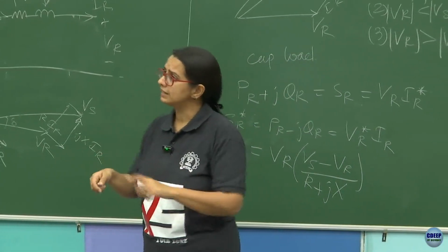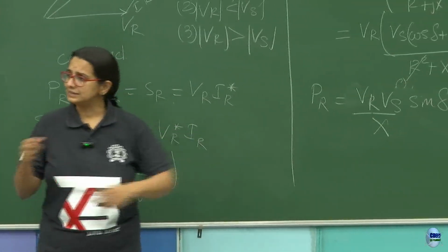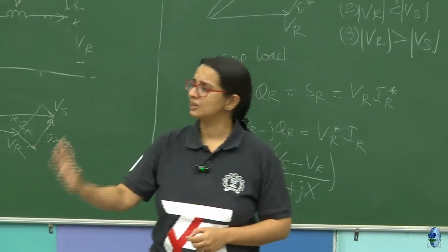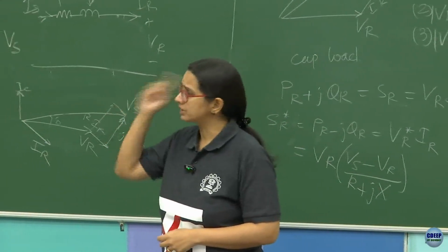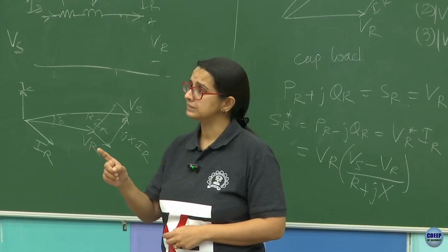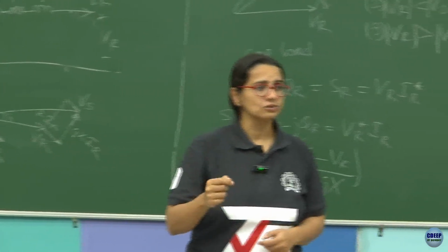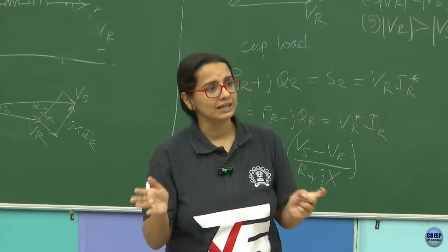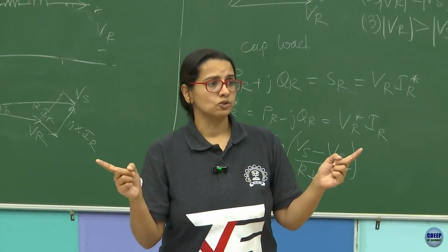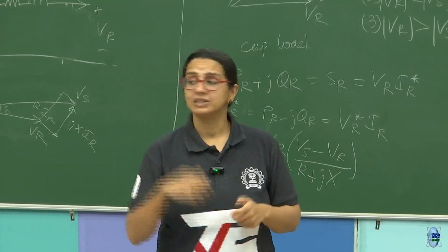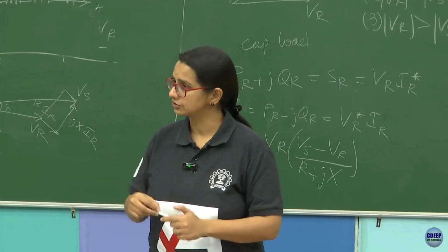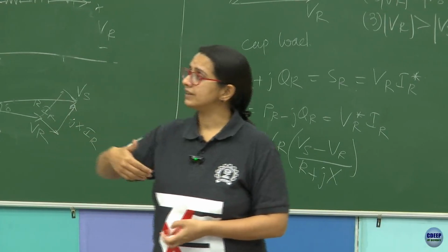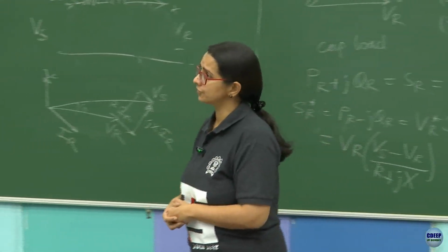And based on that, they're going to look at this and then say, okay, for this corridor, this is how much power you could safely push. It's going to be a function of what corrective measures for voltage are in place, what they think from their intuition is a safe enough delta to maintain across the sending and receiving ends, what they know from the line geometry, what that X is going to be, and so on and so forth, correct? That's how they in fact tell you what that operating limit is going to be.